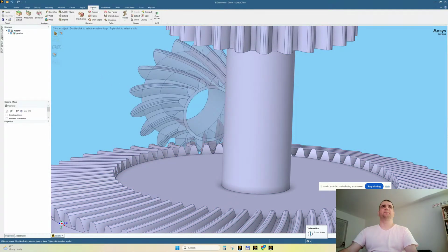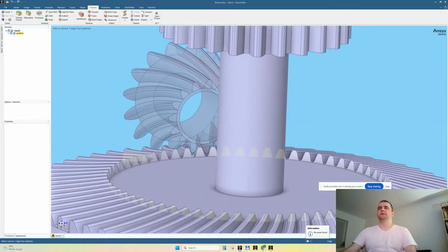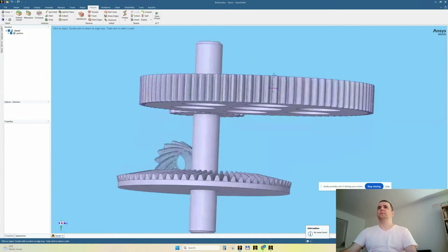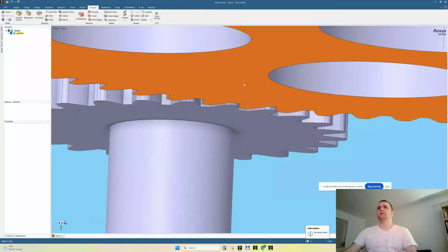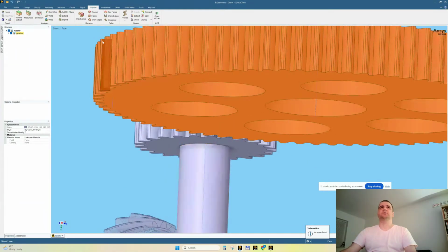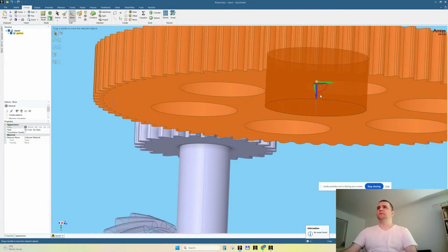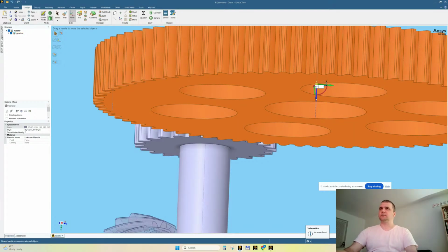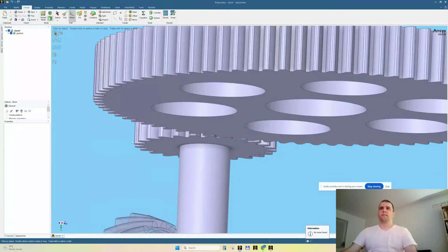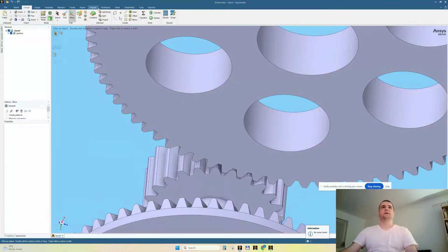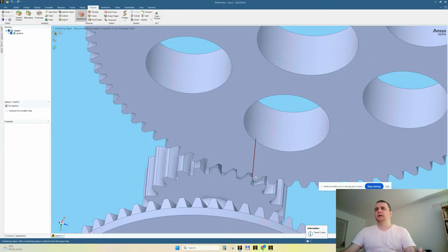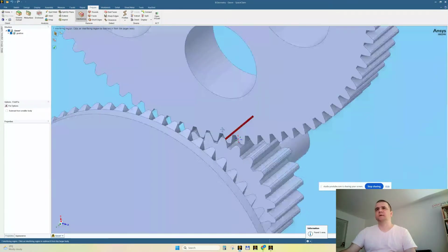All right, so prepare interference. Nowhere else found. So there are no interfering bodies in the model. So we are very well. Only we need to pull this downwards with 0.1. Design, move, and 0.1. Perfect. Let's check again the interference within the entire assembly. Ah, we have an interference here. Okay.